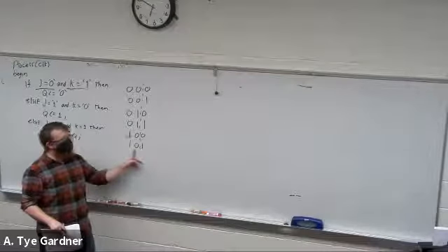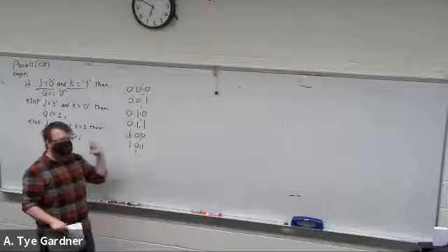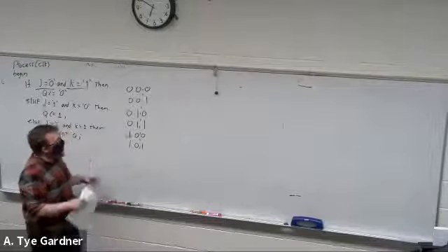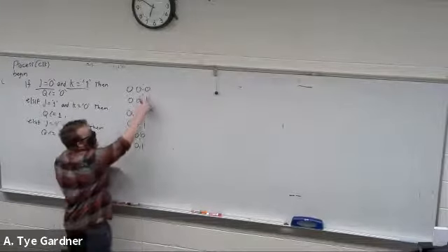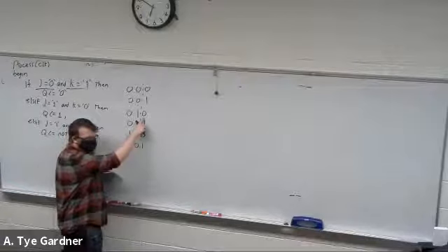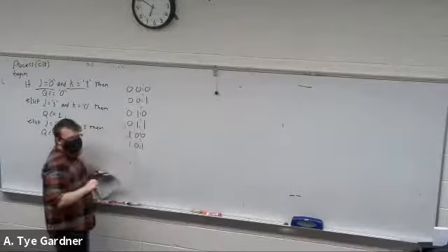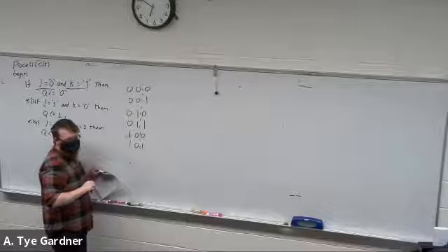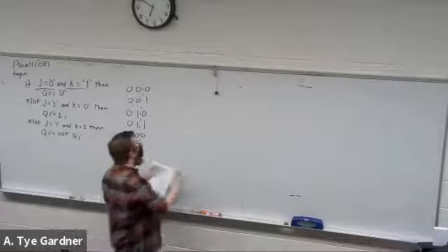In the second column, I only want to change every 2 times. Another way of saying that is really on the falling edge of the first column, toggle the second one. So T for toggle, right? That's all that's saying.